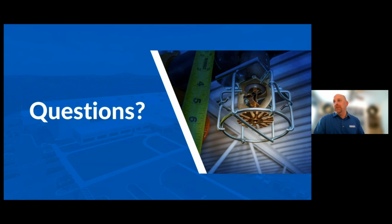Well, it was tested. That's the key. Whatever we make a sprinkler for, or however you make a sprinkler, what you test it for is what you get a listing for. We couldn't get a listing for the sprinkler for lithium-ion batteries. We did everything we could. We took the hazard all the way to exposed expanded plastics, and then we did our own research with the lithium-ion battery to try and prove it out as a concept. And really, that's it. It was tested for it.